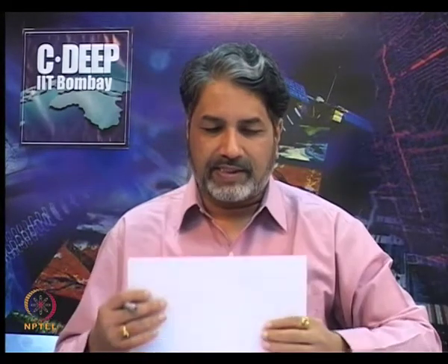So this is the material dispersion now. The next dispersion which we want to investigate is what is called the waveguide dispersion. And as I mentioned earlier, when we now discuss the waveguide dispersion, that means this is a dispersion due to the modal nature inside the optical fiber.